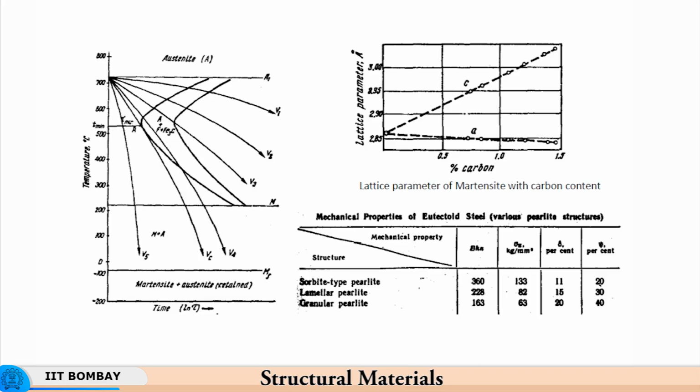There you would like strain induced martensite to form inside the material and then increase the uniform deformation of the material. So the strength goes up, the hardness goes up, and initially the material is soft, something that is desired by the manufacturer. So basically this is again one scheme whereby during working, during its service period, the mechanical properties continue to get enhanced. So you have chemical composition playing a role, the mechanical working also playing a role in deciding the martensite start and martensite finish.